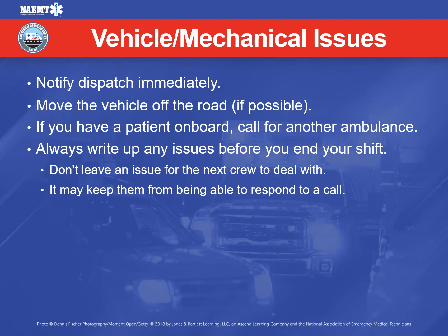Occasionally, an EMS vehicle has a mechanical problem or failure while it's in service. Be prepared to move the vehicle to the side of the road and notify dispatch immediately. Make sure you use your four-way warning lights and carefully place flares or safety triangles as prescribed by the vehicle code. If you are in a dangerous position, notify the police right away.